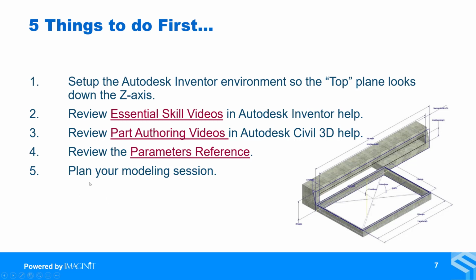And then finally, I say plan your modeling session. Get a look at the typical detail of the structure that you're going to be creating and plan out how you're going to model that. What portions of it are going to be the surface structure? What portions of it are going to be the underground structure? How can you break that up?